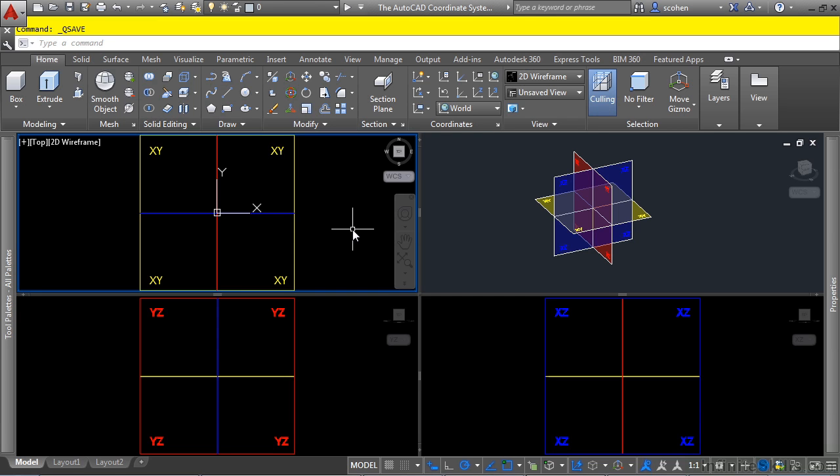When you define a new UCS, you define a new origin location and direction for the X, Y, and Z axes. The way you define a new coordinate system depends on the geometry you have created and the geometry you are trying to create and modify. In some cases, you will have the coordinate system automatically change based on a flat face you hover your cursor over. In other cases, you will manually reorient and reposition the coordinate system. This manual adjustment can be as simple as moving the origin to a new location, reorienting it by picking 3 points in space, or rotating its alignment around one axis.